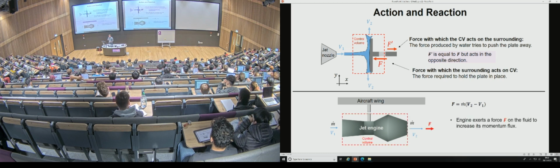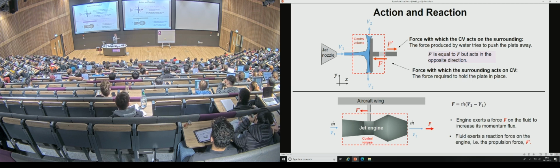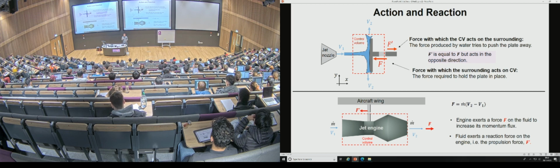The cut in the support is there to emphasize the cut that you make around the object that you're looking at. We said on Monday that the choice of the control volume is central to what you want to be able to answer in the question. And if you're looking to answer what is the force acting on the support, then you should cut it through the support, because the free-body diagram will leave you with a force there.